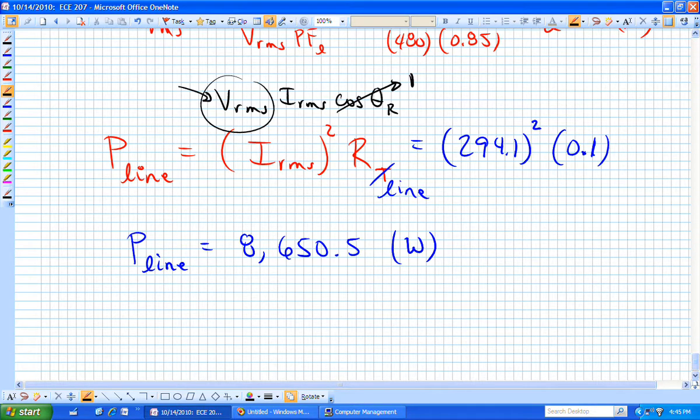Ohm's law. So this is I times R. Where this current is there, there's my I squared R. We just use I squared R because we don't know the V on the resistor. Right, we don't know the V on the resistor, so we just use the formula that will give us the power in the units that are in the variables that we already know. Does that help?